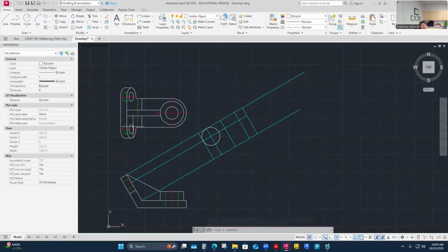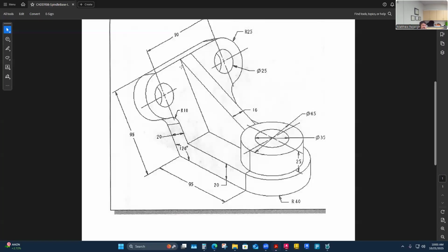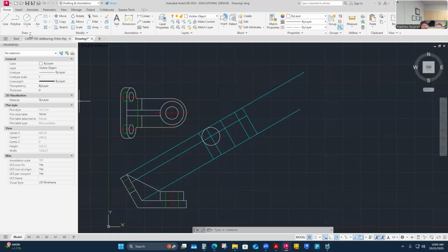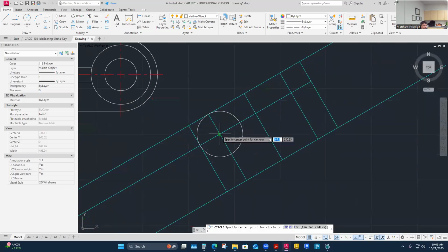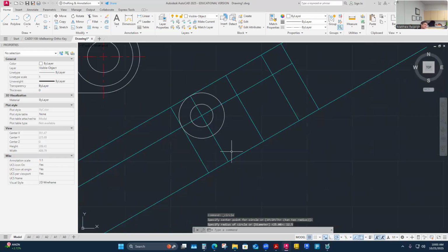Yeah, I did 45 because the spacing on my print here is 90. They're 90 between the two, and I'm working off center, so 45 and 45. That allowed me to get this. I projected this one up from my front view, and then I had that cross intersection, and this. So I've already put my radiuses in. I just need the diameter, 25, or I think 12 and a half, like that.